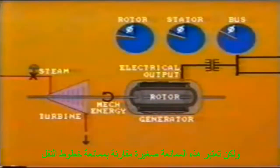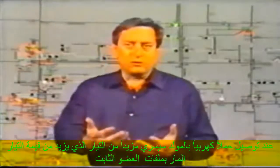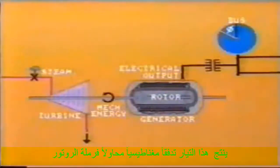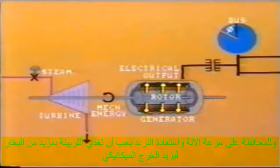However, this is usually small in comparison with the reactance of the transmission line. When electrical load is applied to the generator, more current is drawn, consequently increasing the magnitude of current flowing through the stator windings. This current creates a flux which tends to act as a brake on the turning action of the rotor. In order to maintain the machine's speed and restore frequency, more steam must be supplied to the turbine in order to increase the mechanical output.